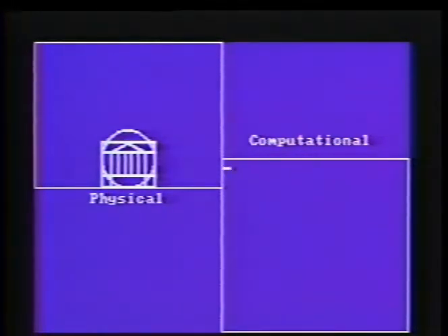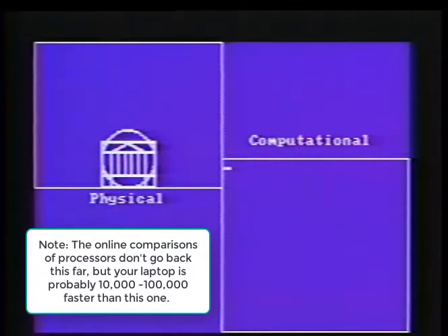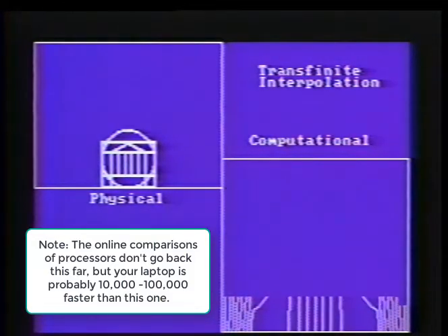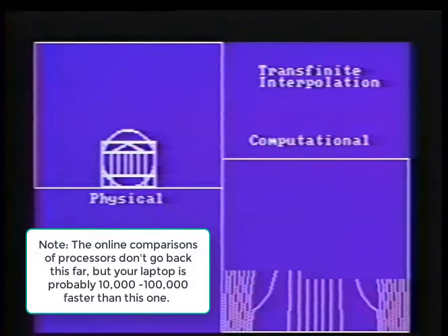To do that, we would map the upside-down U-shaped region from the physical plane on the left into the rectangular computational plane on the right. Then we do our calculations in the rectangular computational plane where the boundary conditions are easier to apply, and we'll map those results back into the physical plane.